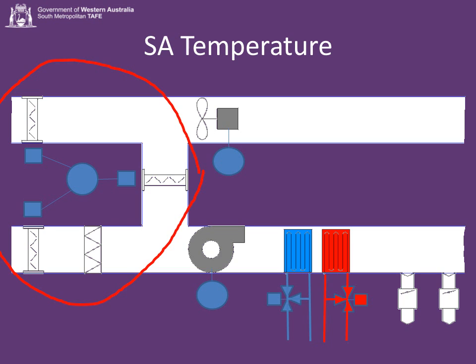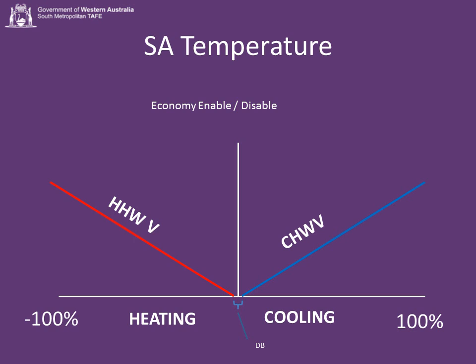The next, much more active way of heating or cooling is to use the chill water heat exchanger and a chill water valve, and the hot water heat exchanger and the heated hot water valve, to modulate those two valves to heat or cool the air. Okay, so I have chill water, CHW, chill water valve, and I have heated hot water and a heated hot water valve. This little diagram is supposed to explain how we would open those valves.